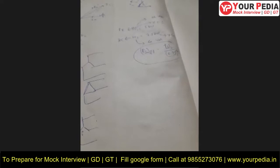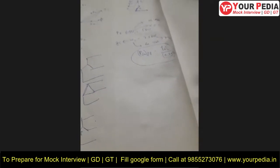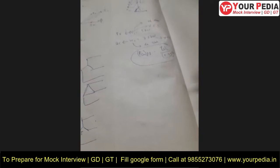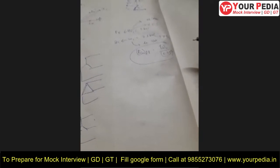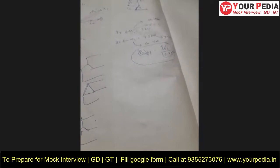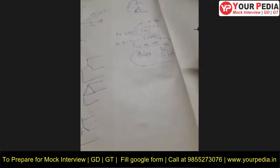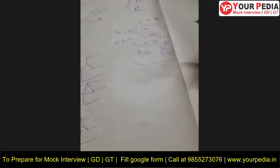Okay. So in the armature periphery, we are using slots. Yes, sir. Okay. So there are three types of slot based on the construction. Can you name them? Yes, sir. Open, semi-closed, and closed, sir. Okay. Of the three of them, which has the highest leakage reactance? Closed, sir.